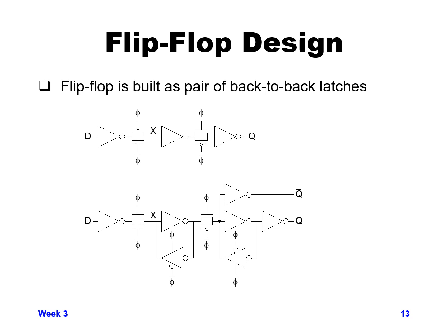What this causes is when clock goes high, the second pass gate, that is the slave, winds up opening up because clock goes high, the NMOS turns on, clock bar goes low, the PMOS turns on, and the master will turn off and capture the value X and hold it during the entire time that the clock is high.